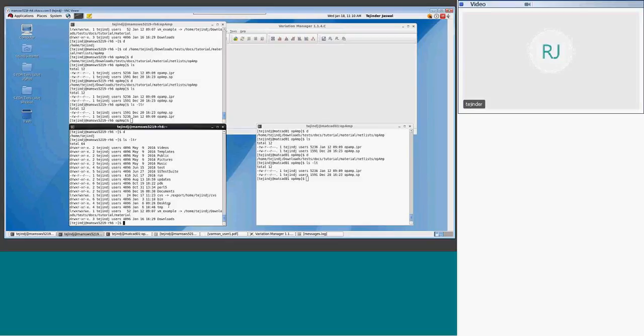So when the design is a little more stable, you can tune to more accuracy and increase the number of simulations, like high sigma, how far you can go: 3, 5, 6, whatever your requirement. That can increase the simulation time too, because it needs more sampling. So once the design is stable, then you can run that, and with fewer numbers you can hold the metrics also.